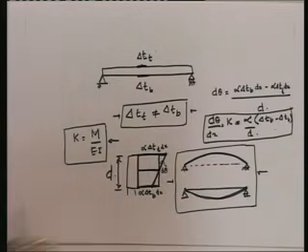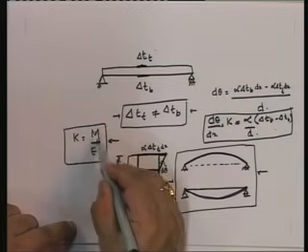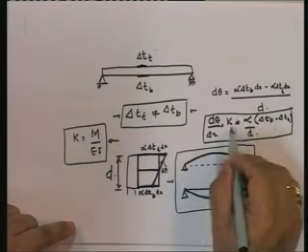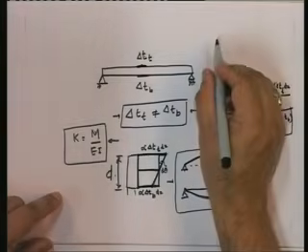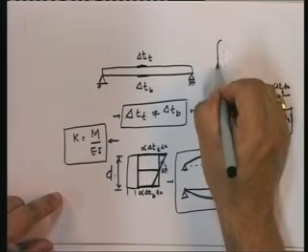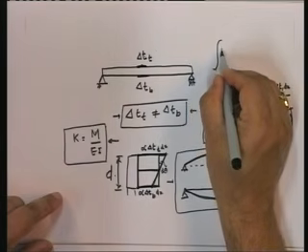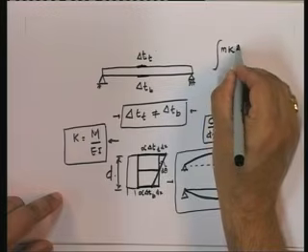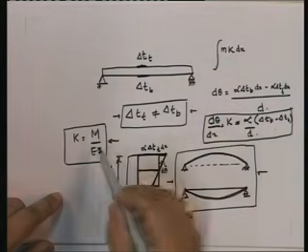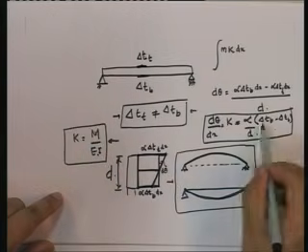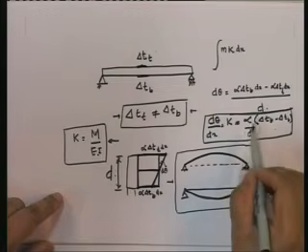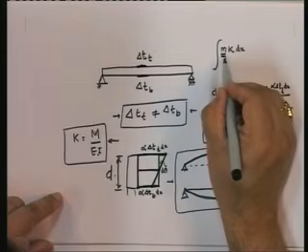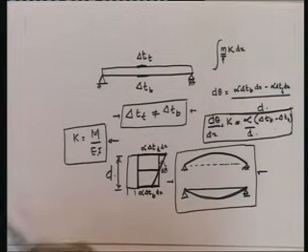When you have loading, this is M, the moment due to the loading, and this is kappa due to that, and therefore virtual work gives us the integral of m kappa dx. So whether that kappa is due to M upon EI or whether it is due to differential temperature, it makes not one bit of difference. This is the virtual moment established due to the virtual force system that we develop in the structure.